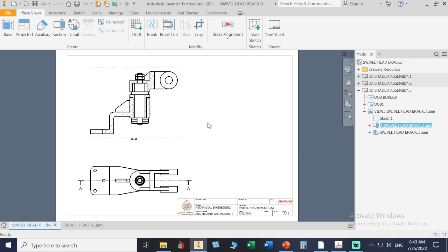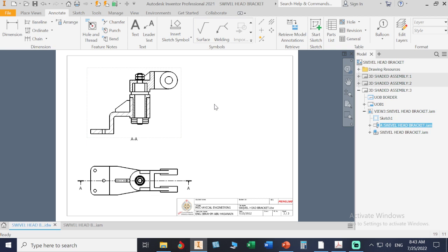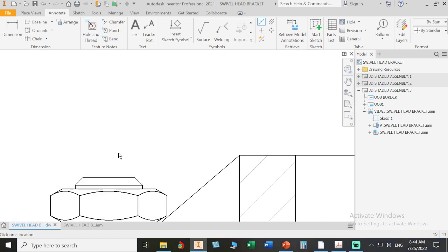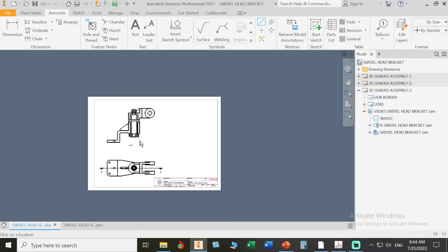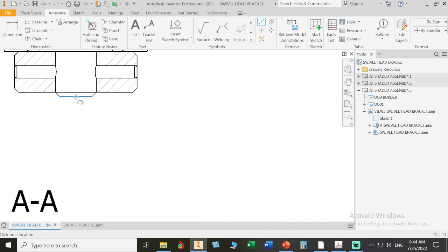Okay, of course you can now add center lines, center points, etc. We have here our center mark. Click any circle, it will have it. Okay, I explained this one already. We have a center line. You can have the center line from the mid of this one, use your wheel for zooming, to the end of my shaft. Right click, hit OK.